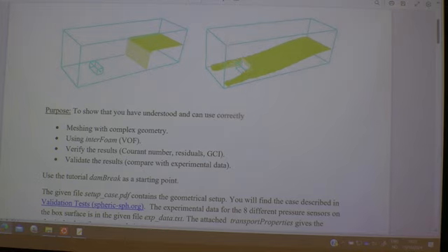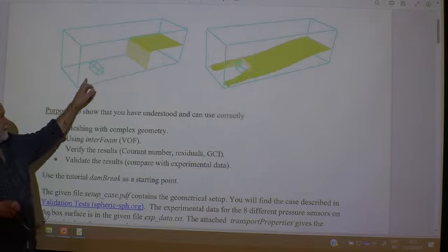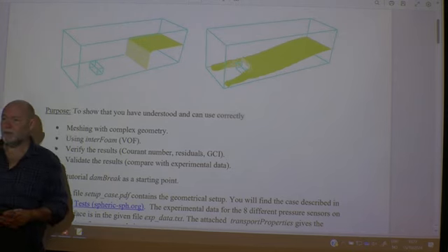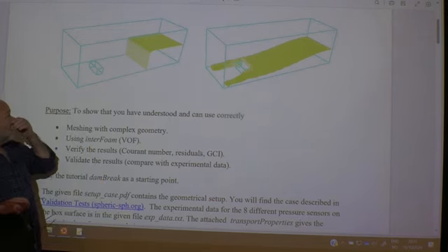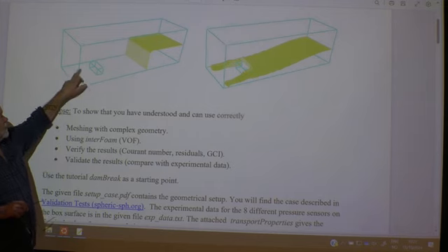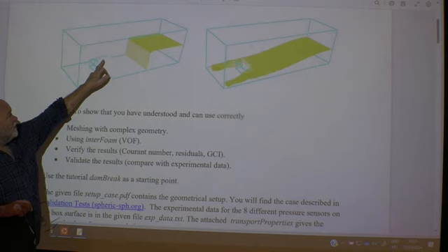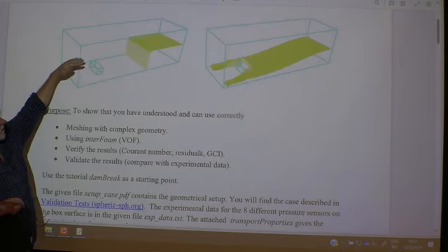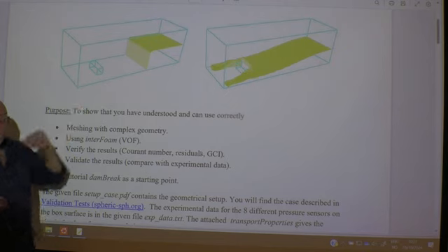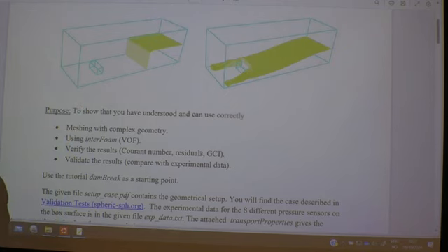And then the third option, if you look at the geometry, you can create this geometry in blockMesh without using snappyHexMesh at all. You're going to need several blocks then. How many do you need? Well, at least 1, 2, 3, 4, 5, 6, 7, 8. And then you need the same amount at the top, 16, and then 1 over this one, 17 different blocks or something like that, to get all the geometry within the simple blockMeshDict. That's also an option for you if you prefer that one. snappyHexMesh can be a little messy, of course.